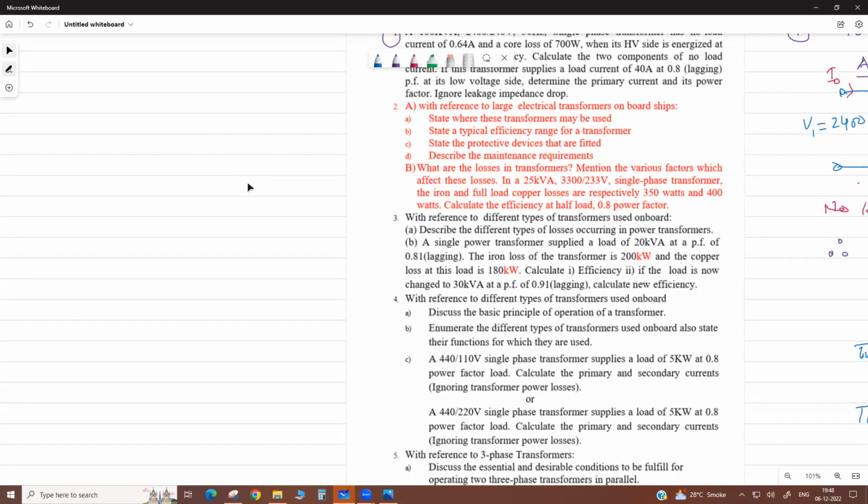Your expansion and when load decreases or increases, when load fluctuates in a transformer, the level of oil in the tank varies. That is, if overload, then heating, then its volume is increased, it goes to the conservator tank. When load is down, then it reduces the volume, then oil flows from conservator to main tank. Then it sucks the air.